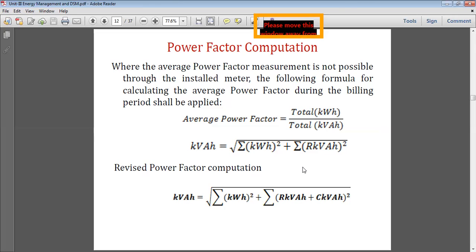For example, in the daytime your factory is running, so you maintain the power factor by connecting some fixed capacitor. But at night time, say only one or two shifts are working, we shut down our machinery, whereas the capacitor remains connected in the system. So when the fixed capacitors remain connected, what do they do? They increase the power factor and push it toward leading, say 0.6, 0.7, 0.8 or 0.85 leading power factor. From our calculations we know that the power factor, whether leading or lagging, will draw more current.